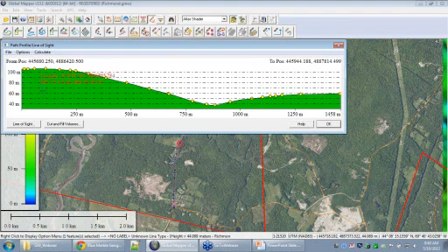And also, as we scroll from left to right here, you'll see my cursor. As I move from left to right, it gives us the horizontal coordinate for the corresponding spot snapped onto that road feature. As well, on the main map view, you'll see a little red X set of crosshairs moving along to the corresponding region on that line segment. At the bottom of the path profile tool, you'll see a couple of the analysis functions that we have here. So we have a line of sight calculation and a cut and fill volume calculation.